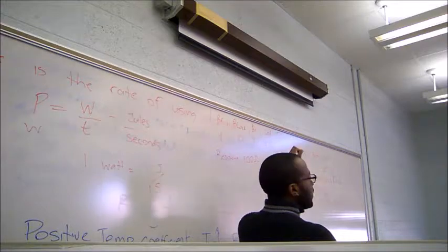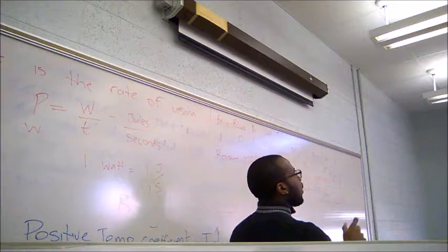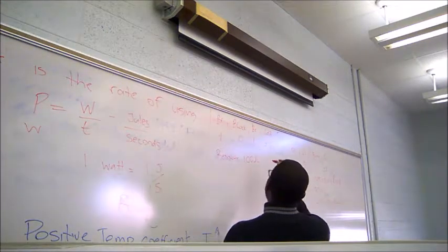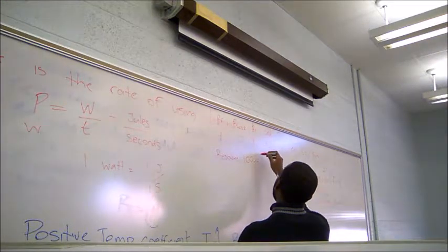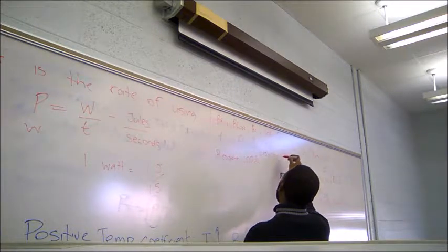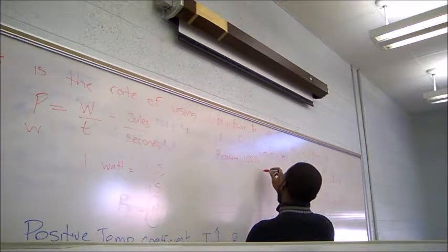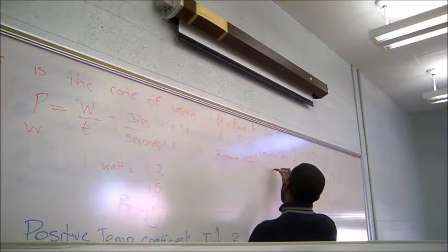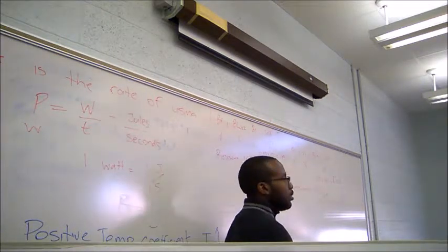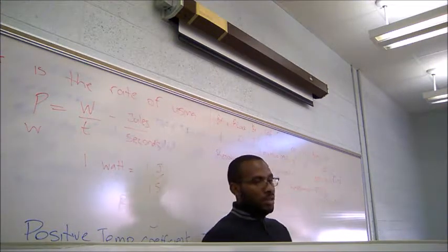So again, this tells us the nominal resistance, but then when we measure it, we see what it actually is. But we can use the tolerance to know what is the highest it can be and the lowest it can be. The lowest is going to be 95% times 100, which is 95 ohms, correct? And we're going to have 1.05 times 100, which is 105 ohms. Okay, does everyone understand this?